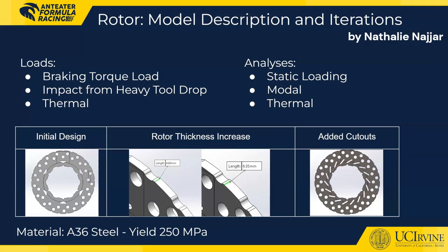I'm Natalie, and today I'll be discussing the FEA analysis of a Formula SAE brake rotor. The goal of the simulation was to evaluate the rotor's performance under different loading conditions, including braking torque, tool impacts, thermal effects, and modal vibrations. We conducted multiple iterations, starting with a base design, increasing thickness, and adding cutouts to assess their impact on stress,